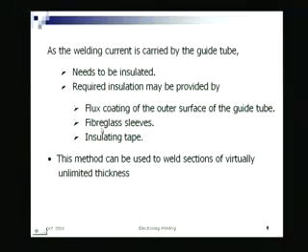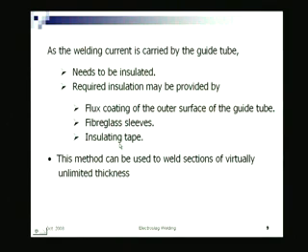Now, if you insulate with a fiberglass sleeve, then what happens to that sleeve? Where does it go? It should melt and should float up as a dross. It cannot go in the molten metal, isn't it? Or any insulating tape, if I use, the tape should burn out and float out in the slag as a dross, as an impurity in the slag, right. And also it should not generate any undue fumes or gases which may get entrapped.